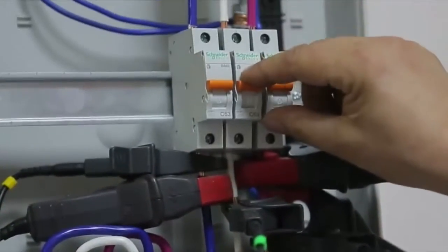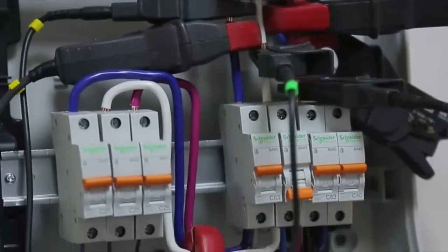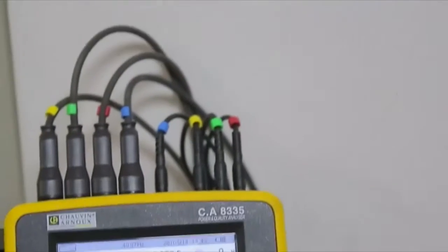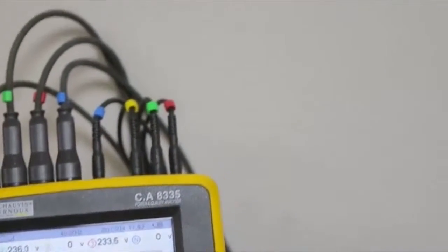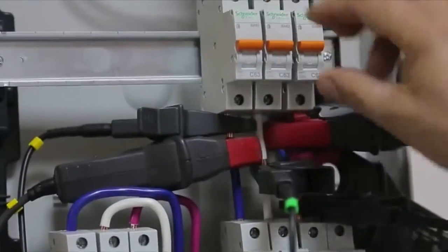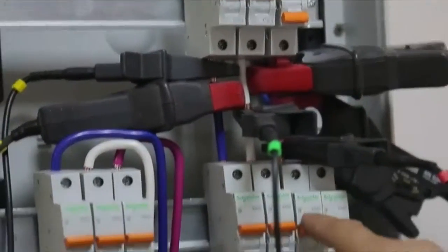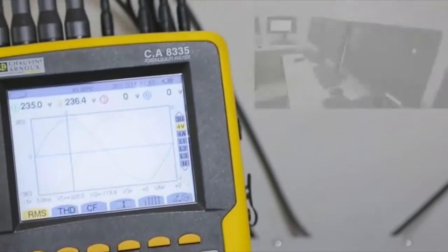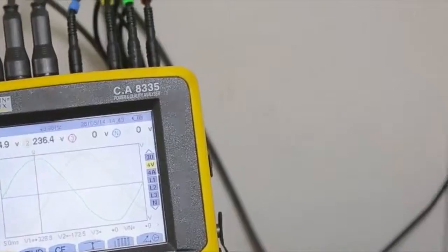Now, disconnect phase B by 2 single-phase automatic circuit breakers. Phase B is disconnected but servers continue running. Reconnect phase B. Disconnect phase C. Observing no phase, but operation of servers is stable. Restore original condition of the three-phase system.